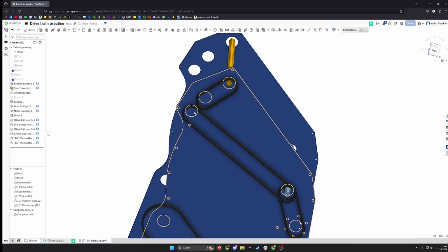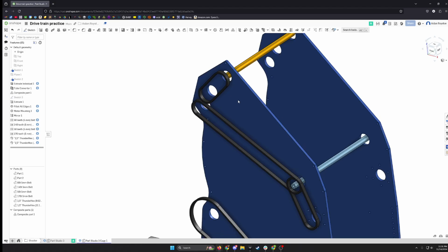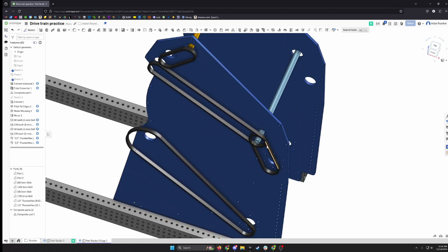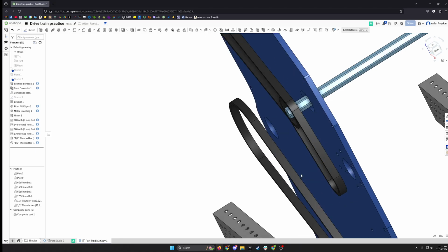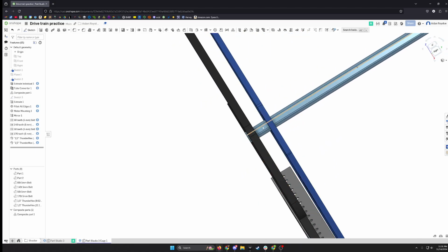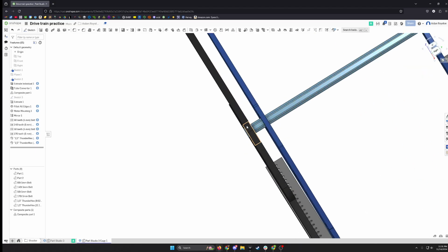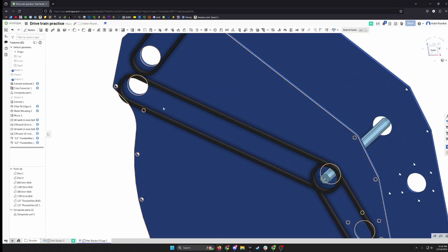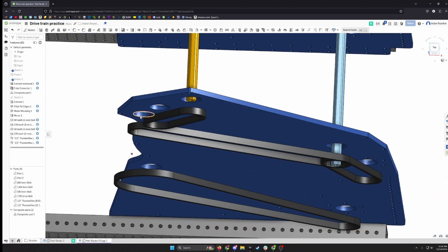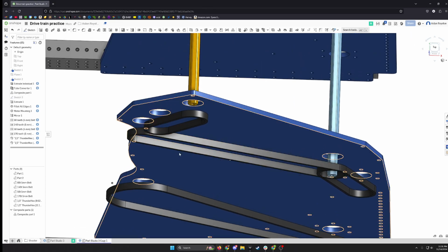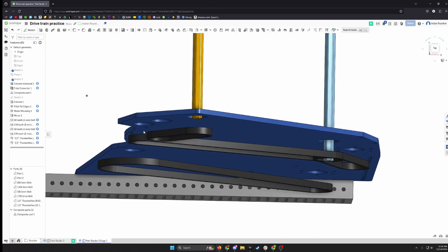And so now we can get back to this one up here, now that I've explained that. And so you see how there's 2 belts. This belt is going to go from the motor. It's going to be the first one, the inside. So we're going to have this one here, and we're going to have the belt going to the gear shaft on the outside. And so we can't just have this be directly just 1/2 inch off, because we have to have a spacing for it later. So we're going to create a new shaft.